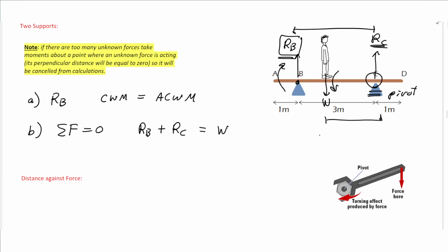In other questions, the forces could be right and left. So the forces to the right are equal to the forces to the left. So any moments question that states that you are in equilibrium, or whatever means that you are in equilibrium, for the first unknown, you use clockwise moments equal anti-clockwise moments, and then for the other unknown, you use that the resultant force equals 0: forces upwards equal downwards, or to the right equal to the left.